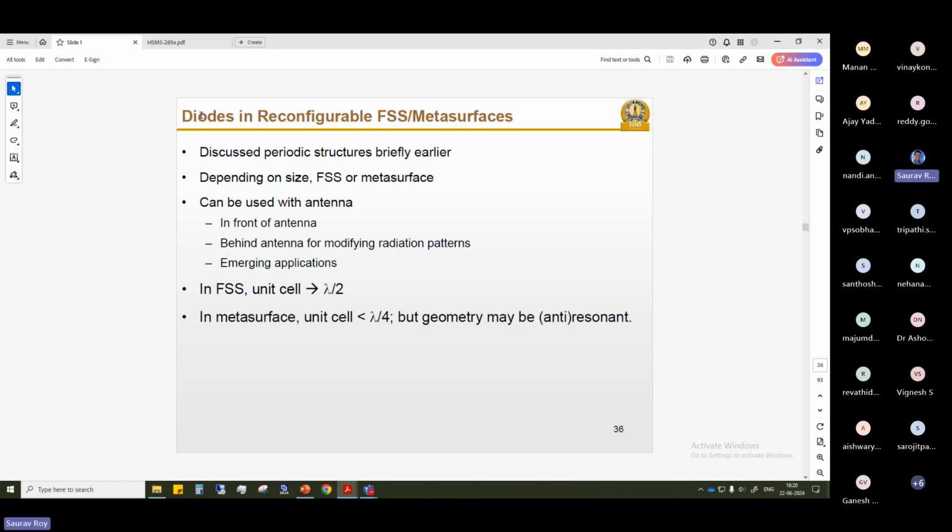Many of the works currently done with normal or conventional lines, like microstrip line based circuits, can be done with metasurface or FSS. FSS is nothing but the frequency selective surface, and similarly a metasurface is made of multiple unit cells. Those are quite similar, and there are multiple applications, because you can bring out multiple applications together with this kind of surface. You can even attach diodes or define switching elements on the surface, which will make it a reconfigurable metasurface, right?